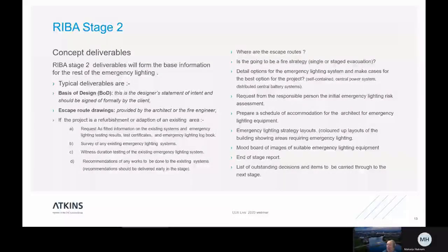There, the BS 5266 says you should not put your emergency lighting in the switch room with the electrical feed, and you can think why that should be the case. If there was a fire in the switchboard, you'd also take out the central battery system as well. So it should be in a separate space, fire protected space, away from the switchboard.